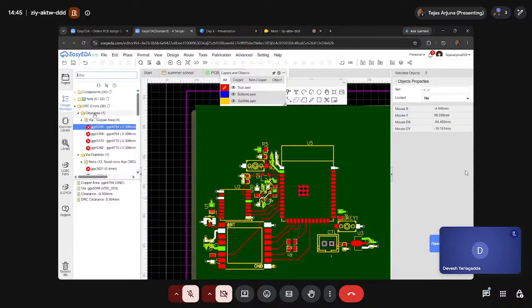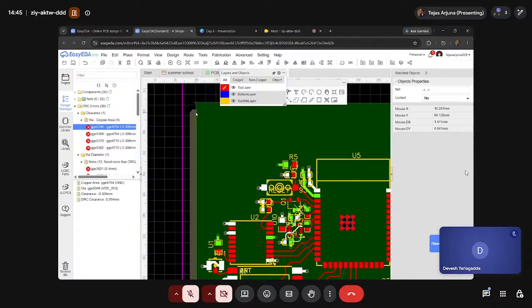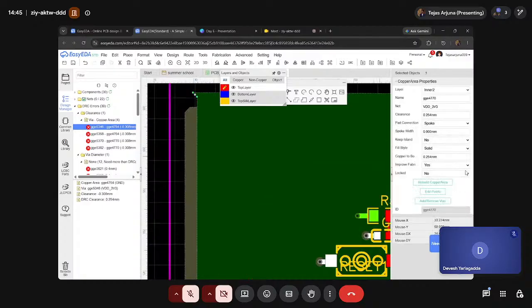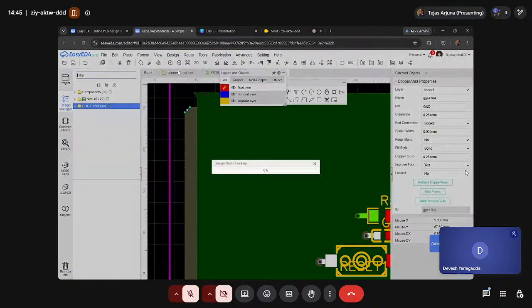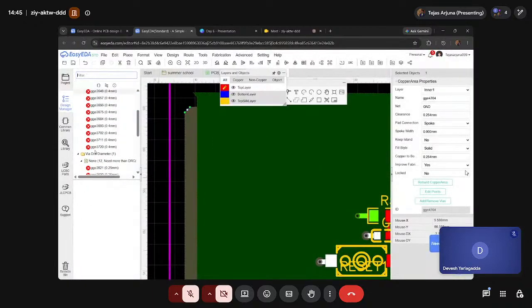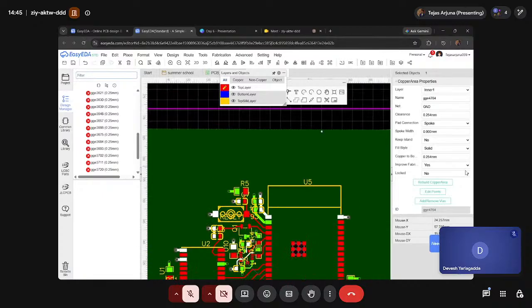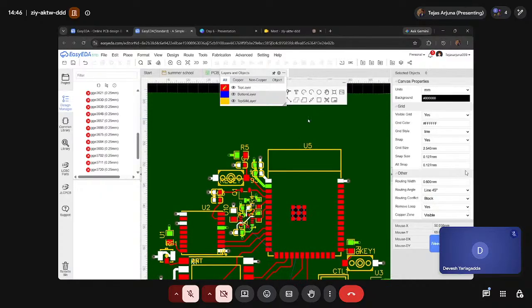Okay, the clearance. We did not rebuild the copper area, right? That clearance. Every time you do this, rebuild the copper area. That is important. Then 26, 24 are from this, and 26 is from that, and the two more are the incomplete connection. So we'll see how we can fix them.